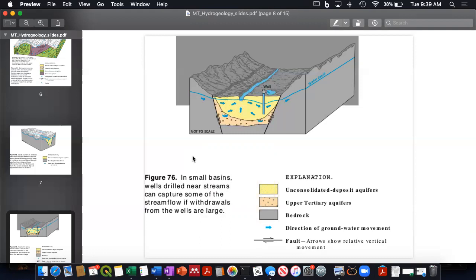So it's important for us to understand what kind of rock was deposited, how the mountain blocks were formed, what kind of faults we might expect. And then recent geologic history is really important because we need to know something about these unconsolidated deposits. So tertiary through quaternary, what is controlling the depositional environment for these sediments.